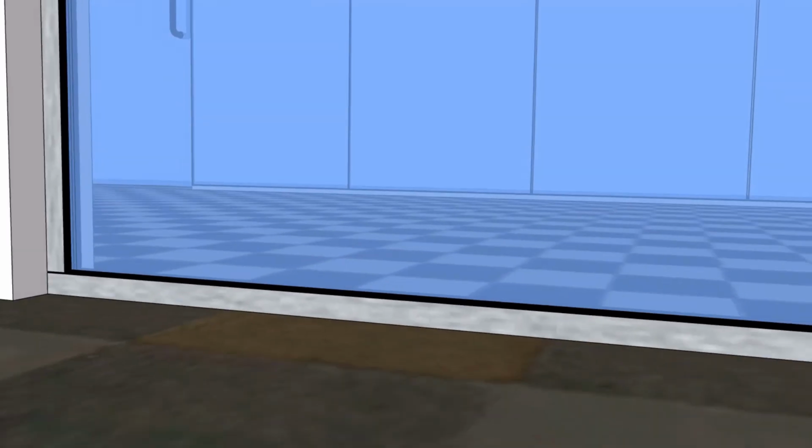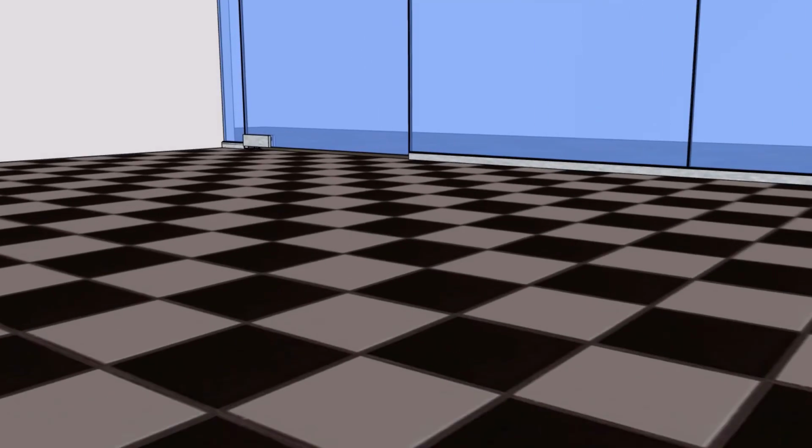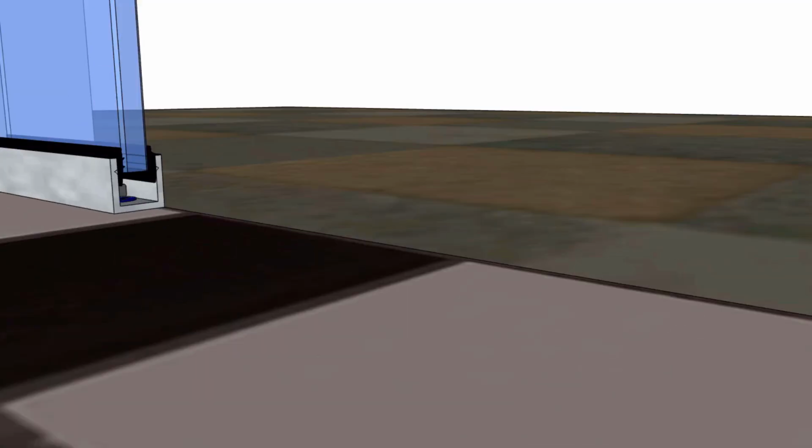Receptor elements do not receive caulking along their length, but they may receive caulking where their ends are cut short. The cut ends of receptors should not be exposed in the finished state. Cover plates matching in finish to the receptor should be applied to the cut ends of receptors where they would otherwise be exposed. The thickness of cover plates should not exceed 40 thousandths of an inch.